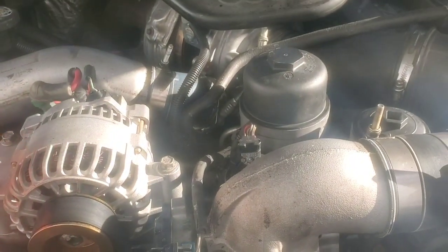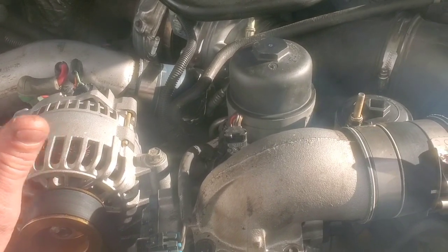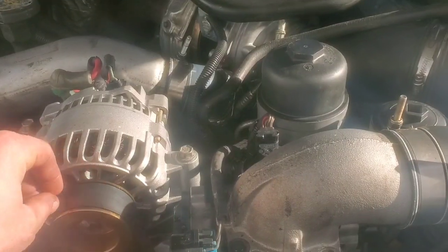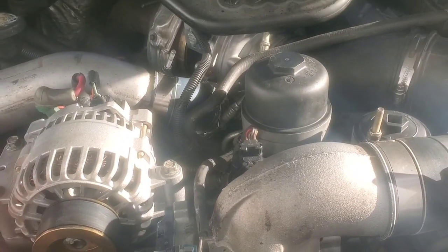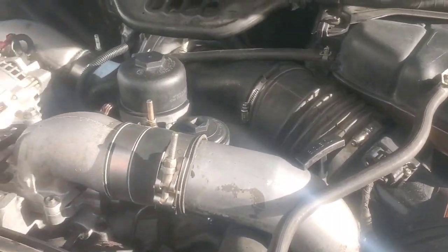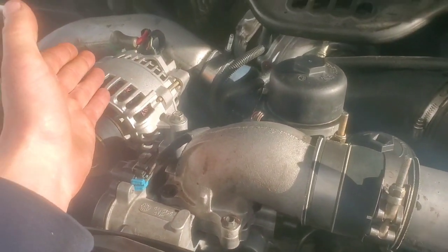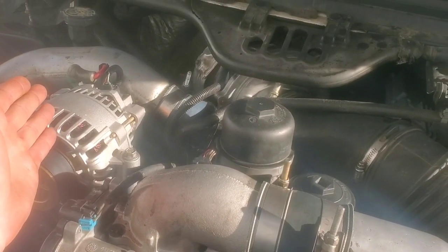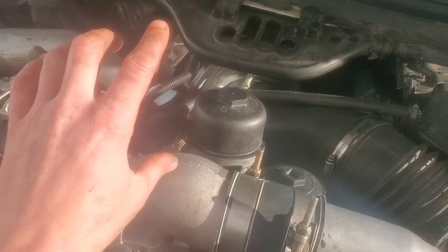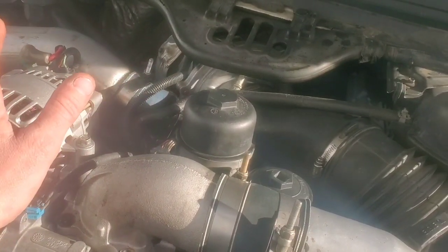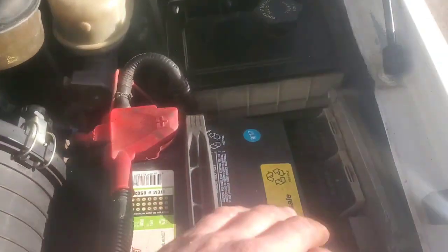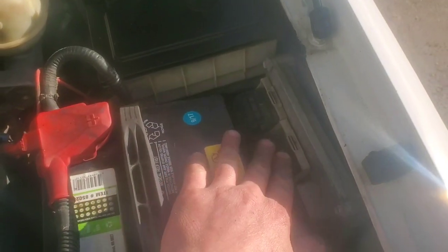These engine wiring harnesses are readily available for $250, $350, somewhere in between. I've used some aftermarket ones in the past, and it's worked just fine. Basically, the wiring in between the ICP sensor, and that's pretty much what we're dealing with, is that I don't know what's going on with it losing certain parameters at different times. I don't know what that's all about, but what we're going to end up doing is replacing the engine wiring harness that goes to this ECM here.